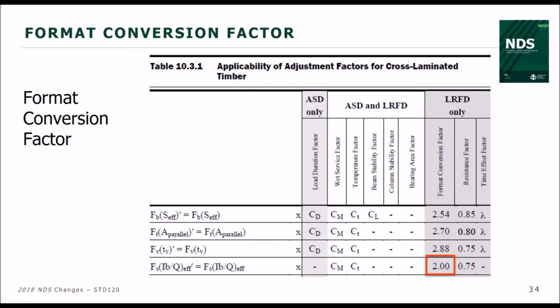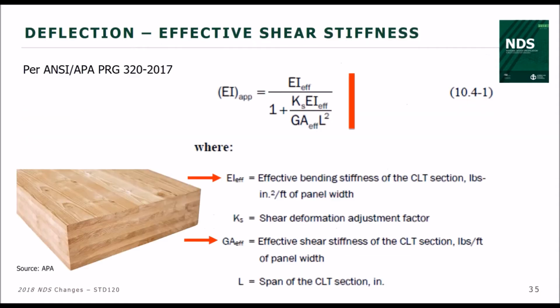And that ASTM D5457 is the standard specification for computing reference resistance of wood-based materials and structural connections for LRFD design. So to be consistent with that.